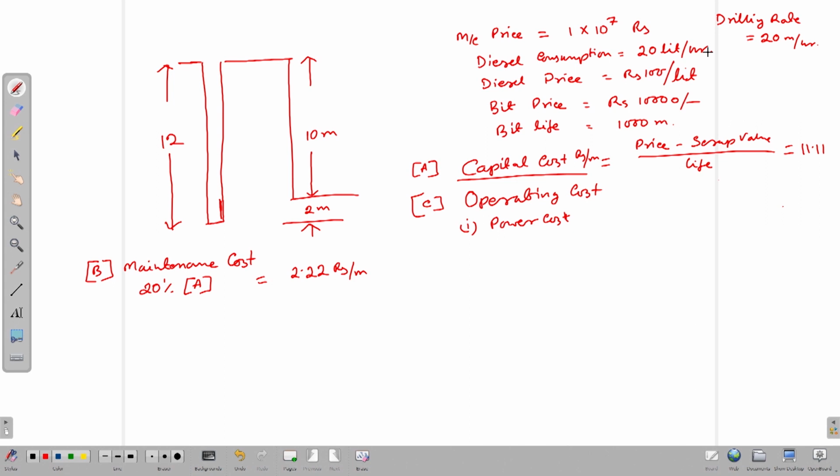That is why you can understand, if your engine is on and you are not putting the vehicle in gear, the fuel will be consumed, even if the vehicle is standing at one place. So, fuel consumption is not related to the kilometers run, it is basically depending on the hours for which the machine is running and the load on the machine.